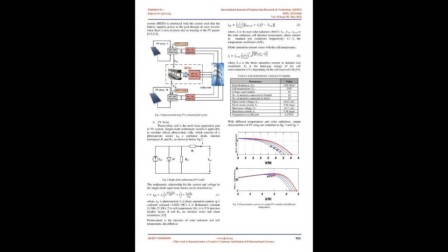The current paper discusses a topology of a multi-array connected solar energy-based PV installation with integrated battery energy storage. The PV system under examination is divided into several sections, and each part has its own DC-DC converter and a 2-level DC-AC inverter with grid-oriented voltage control as seen in preceding sections. In the proposed plan, the 2-level inverters are used to obtain a voltage waveform comparable with that which would be available from a multilevel converter 8-9.